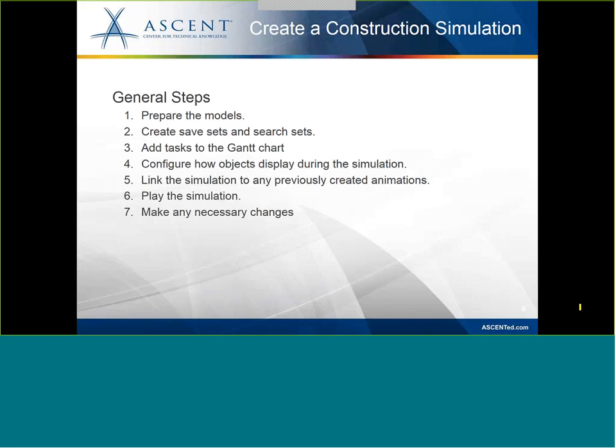Then you need to take that information and create some save sets from it and search sets. Chapter 4 teaches you how to do that. I'll show you one or two today just so that you can see how important it is. You need to be able to tell it, I want all my windows in during this week of construction. So I would save a search set of all your windows to simulate that coming in during that week.